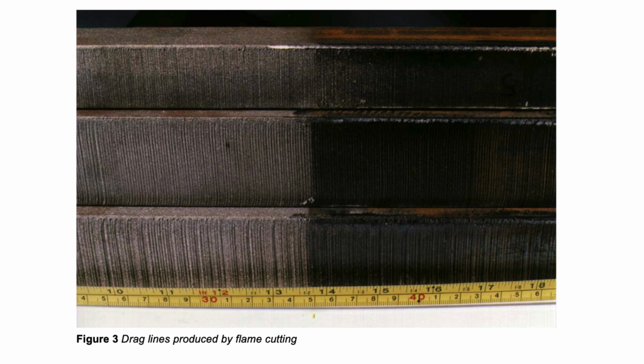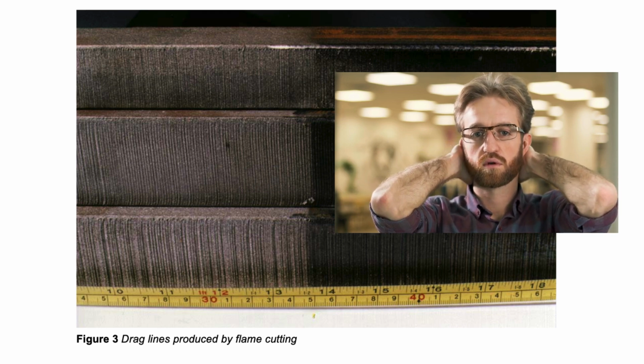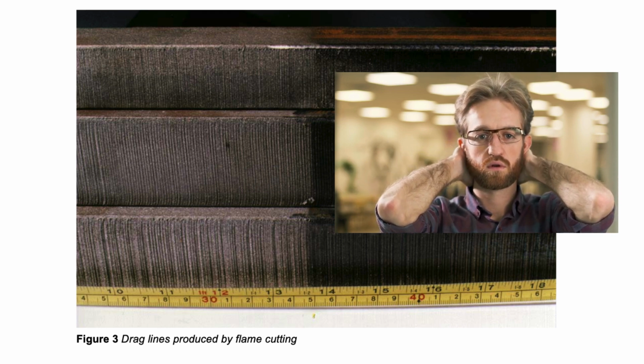When equipment settings are perfectly adjusted, it is possible to produce a cut with an extremely smooth and flat surface, where draglines are not readily apparent, i.e., the serrations are very shallow, or the depth of dragline is small. However, maintaining all the variables within the bounds that produce this standard on components of the scale encountered in bridge work is very difficult, and draglines are usually evident to some extent.